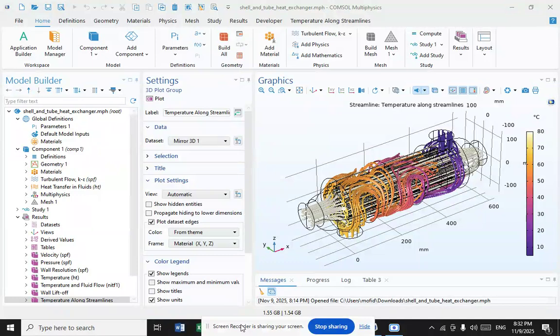The tube thickness of the wall of the tubes is usually determined to ensure there is enough room for corrosion and that there is resistance to fluid-induced vibration. The next is axial strength, availability of spare parts, hoop strength to withstand internal tube pressure, buckling strength to withstand over pressure in the shell, and next topic is tube length.